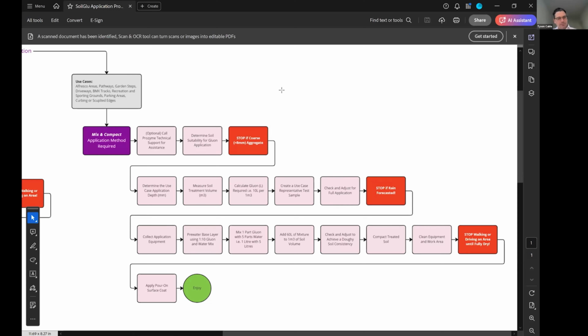But with Polymag, you don't have to do any of that prep. You can just come through with Polymag, spray it directly onto the surface of the road and drive on it instantly. You're not doing anything, just pouring it on and driving on it. And that is effective up until the first heavy rain. So if you do it at the start of dry season, you should get through nearly the entirety of that dry season with just one application.